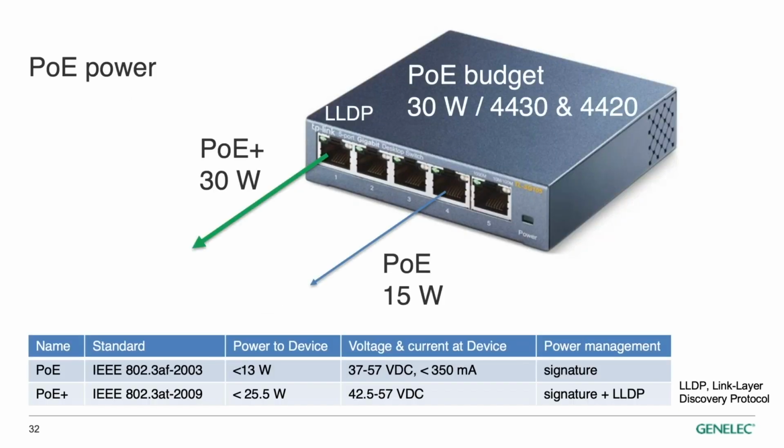Each loudspeaker requires 30 watts of power from the switch. PoE Plus is an IEEE standard, delivering 30 watts out of the port on the switch. At the receiving end at the device, if the cabling is long, you get a little bit of power loss and you receive 25 watts roughly at the loudspeaker end.